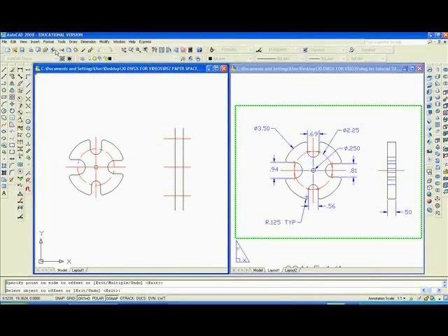And we'll use the paintbrush to put everything on the picture in the same layer. And then we're going to escape, fillet, F, enter, radius, R, enter, 0, 0, enter. So now that fillet is radius 0, we can try it again. F, enter, and clean up the intersections.